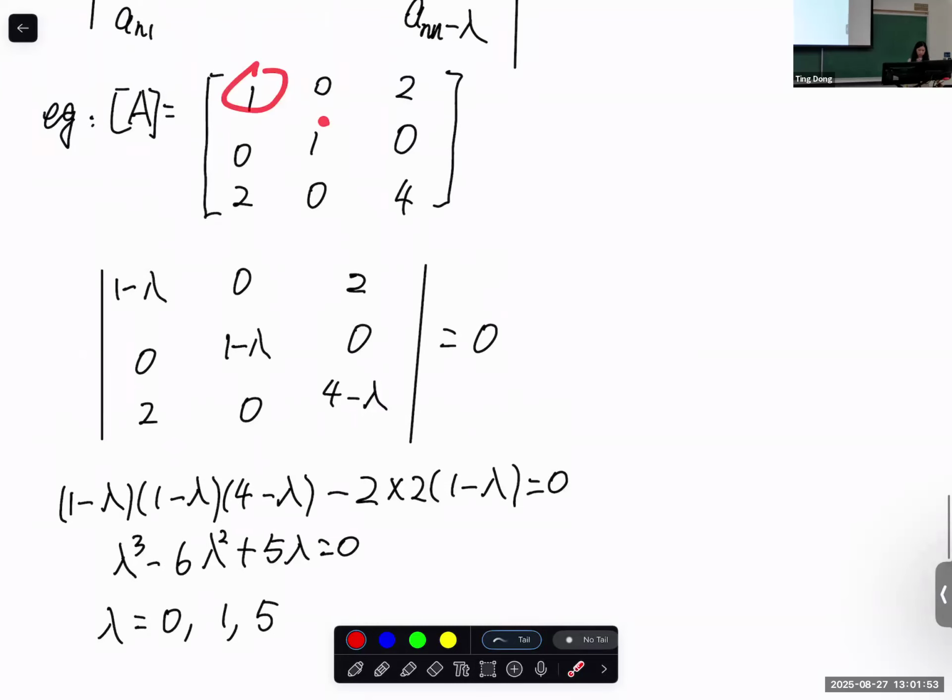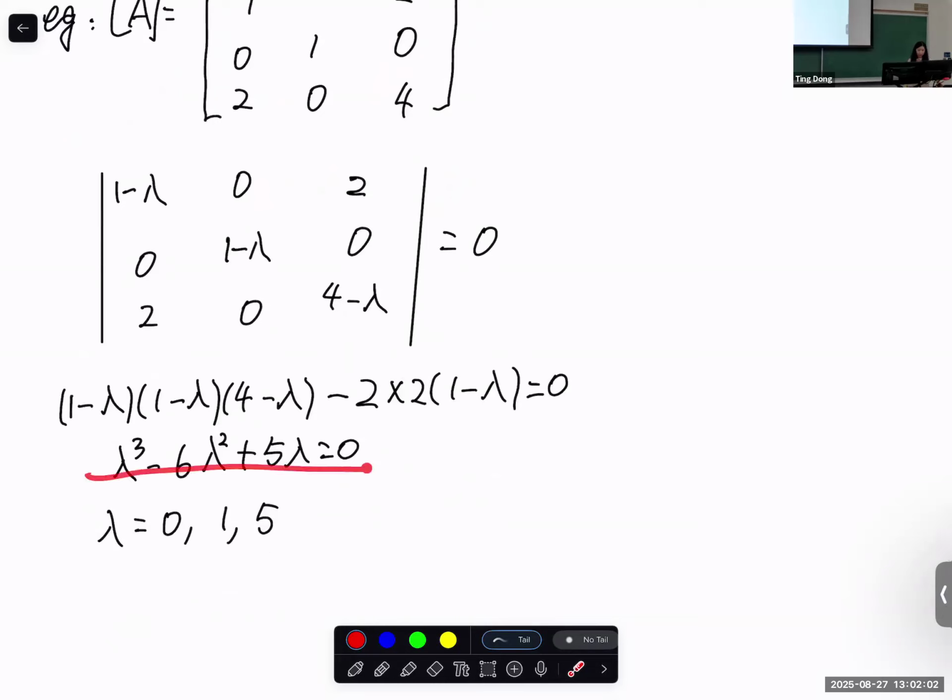Let's say these are the 3 normal stresses sigma x, sigma y, sigma zz, and this is the tau xz. Then you calculate principal stress, and you calculate 3 eigenvalues, and the principal stress normally puts the maximum one as sigma 1. So this becomes sigma 1, sigma 2, sigma 3, right? It's the same thing. Any question?